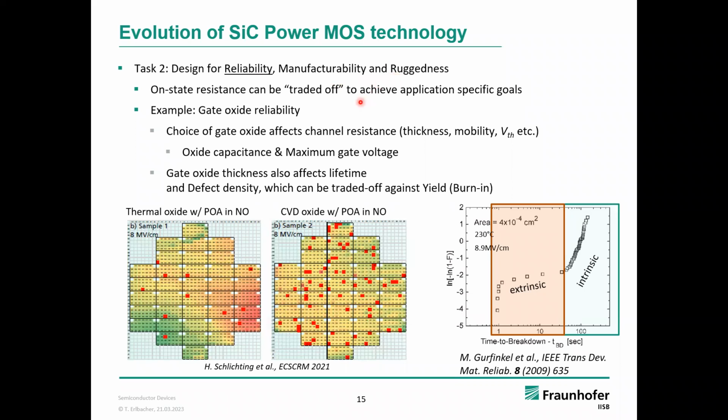This is achieved by ensuring typical reliability, for instance for the gate oxide, through gate oxide screening and burn-in tests; the substrate defects or epi defects play a major role and have to be investigated. Most of the know-how that we have from silicon, we can transfer to silicon carbide, like the TDDB tests, but there are additional tests, especially to consider faster switching compared to silicon IGBT, for instance, that are usually added on top to ensure that these additional